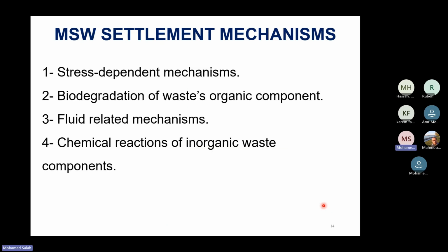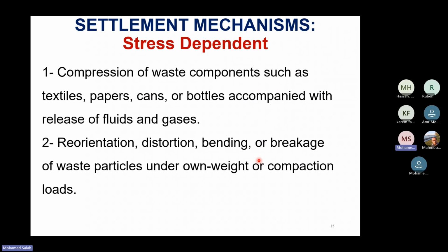Now let's see what are the different settlement mechanisms for municipal solid waste. First is the stress-dependent mechanism. Second is biodegradation of the waste's organic component. Third is the fluid-related mechanism. Fourth is chemical reactions of inorganic waste components. Let's start with the first mechanism, which is the stress-dependent settlement mechanism.